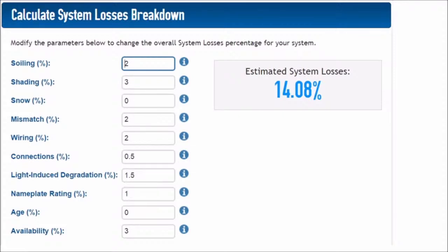As far as shade goes, I recommend using commercial software to build a 3D model and perform shade analysis based on that. For snow, one simply needs to discount the winter season, perhaps entirely, if it can be expected that snow will sit atop the solar array for an extended period of time each year.